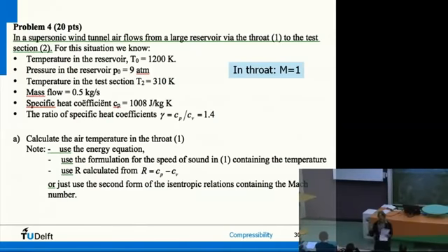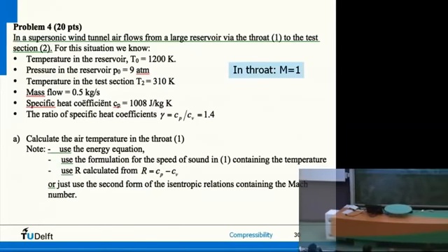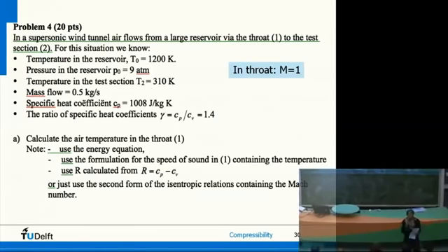So once you have a supersonic wind tunnel, with conditions such that the flow is speeded up to supersonic flows, you will have Mach equal to 1 at the throat. It sounds a bit mysterious, has to do with the characteristics of your flow physics and the speed with which information travels. Believe me, you'll see in the instruction.